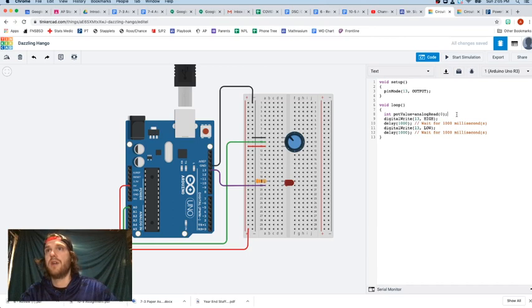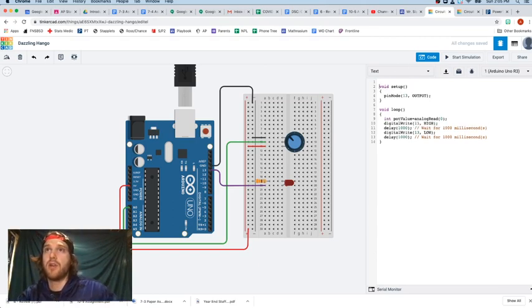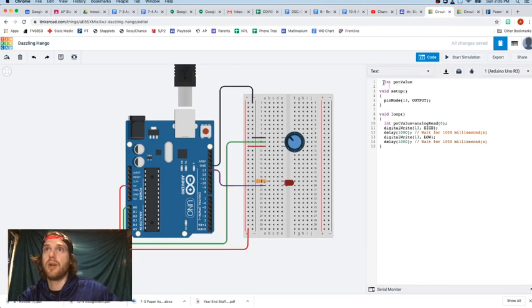So what this does is it creates an integer, and really you could also have created it up here in the preamble if you wanted to. You can come up here and say, for example, copy, paste in the preamble, int pot value. You've created this integer, and then down here you don't have to say integer anymore because you've already declared what it is in the preamble.